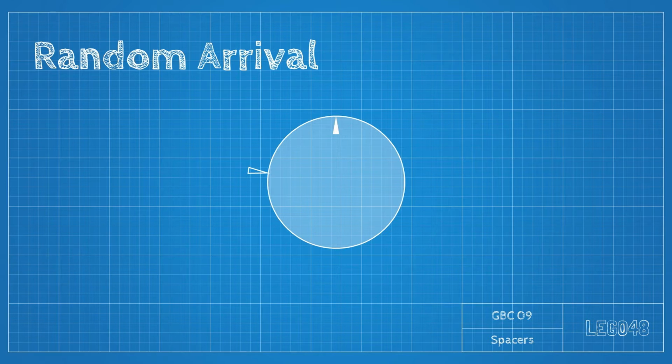If your module is being fed by another one that is feeding balls at approximately 1 ball per second, chances are that the exact frequencies are going to be off a little. If the cycle time of the previous module is a little slower than mine, then the arrival point for each successive ball will be just a little bit later. If the cycle time is faster, then each ball will arrive a little bit earlier in the cycle. If this continues long enough, then the arrival times will continue to shift around the cycle, and while they may not immediately hit the jam point, like a spirograph drawing loops, it will eventually come around and jam.